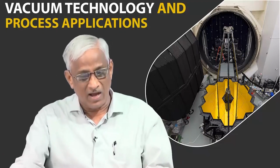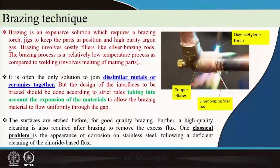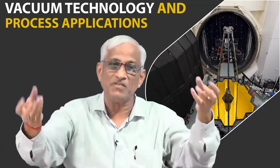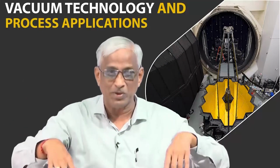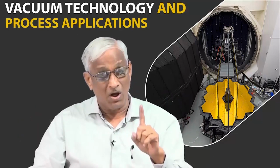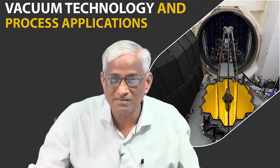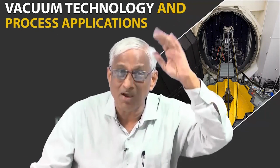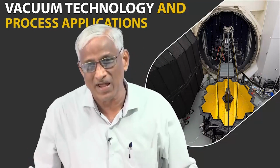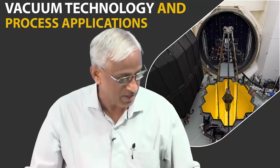So, if you can take care and with proper understanding, you can reduce the budget and make a very good brazing, which is routinely being done in vacuum technology, in small couplings to be joined to the vacuum chamber, which were originally welded. And if it is stainless steel, sometimes they do welding, sometimes they do brazing. So, it all depends on your convenience. If weights are not much, you can just do a brazing, but all should be compatible with the vacuum level. If it is ultra high vacuum, all welding is better. If it is extremely high vacuum, monolithic chambers may be better. So, it has to be thought over according to the level of sophistication required.